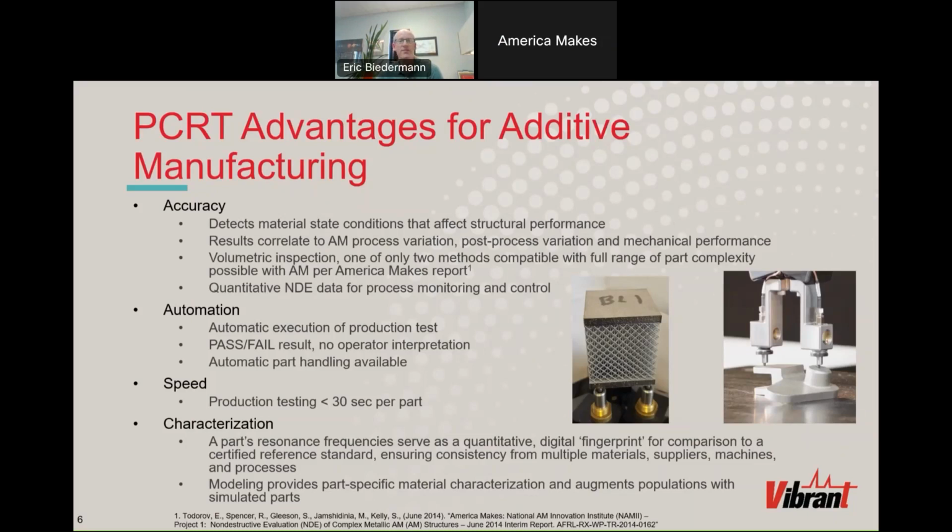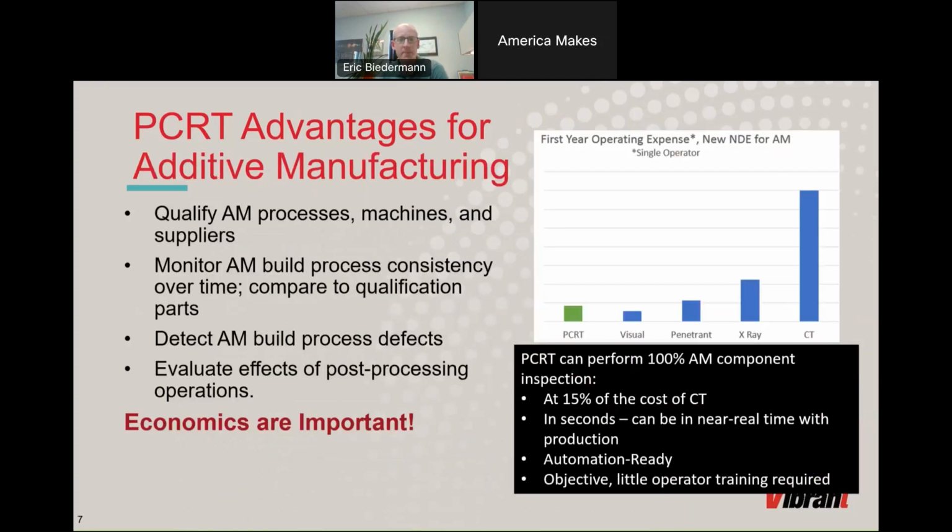And then we also have a lot of capabilities for modeling and simulation tools. So taking a 3D solid model of a part, predicting its resonance frequencies, and then using that for comparison to physical parts. We can also use it to augment reference populations, characterize material properties, and so on.